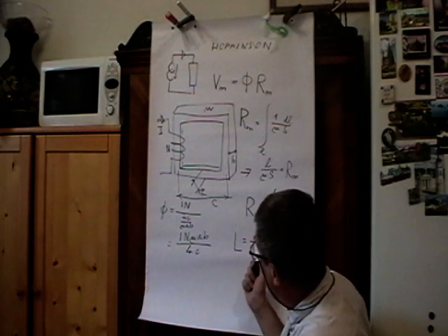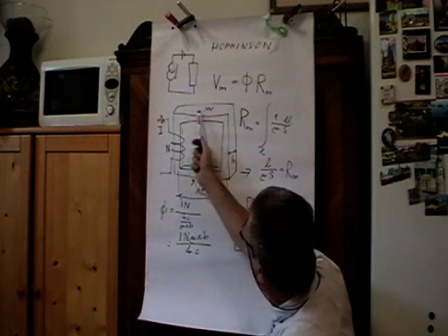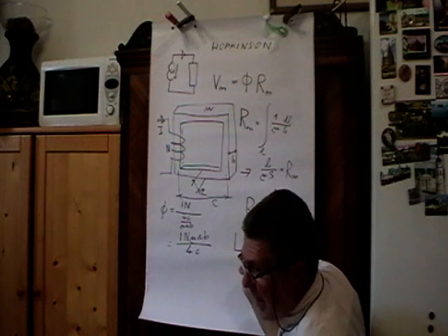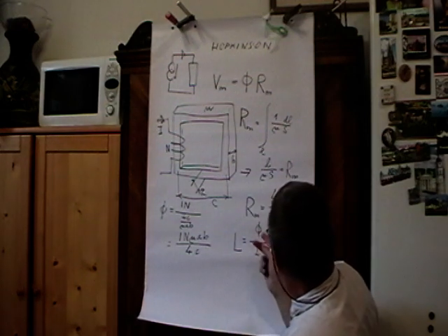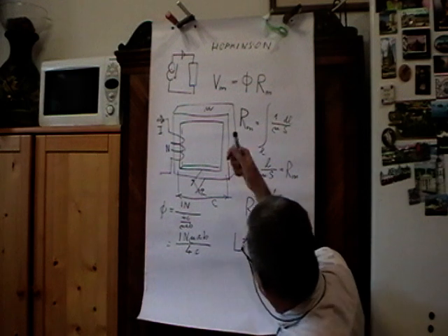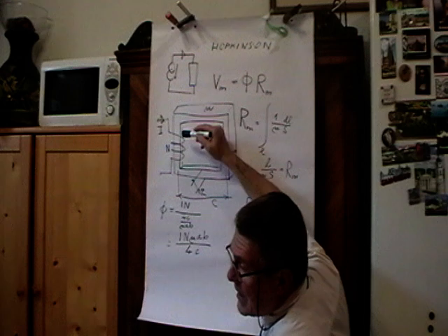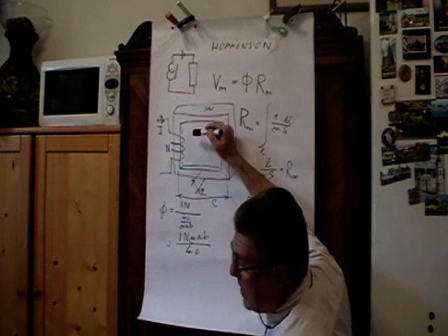This is the magnetic flux that flows through the magnetic core. So if you cut the core at any point, you would get this flux through the cross section. While this phi is the flux that flows through the inductor altogether, and it counts when it passes through each turn of the inductor.